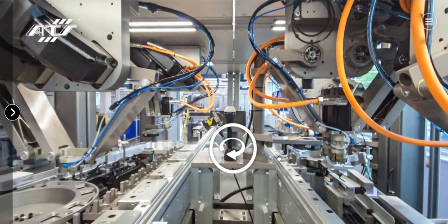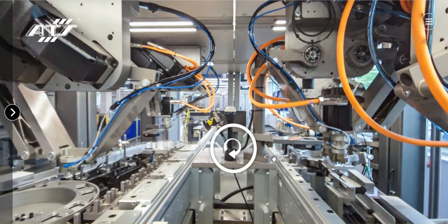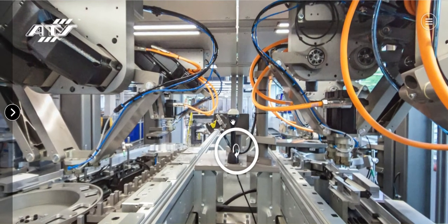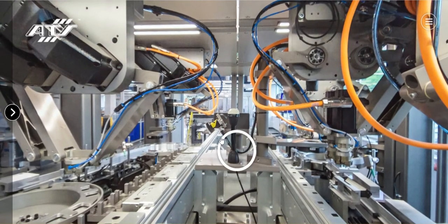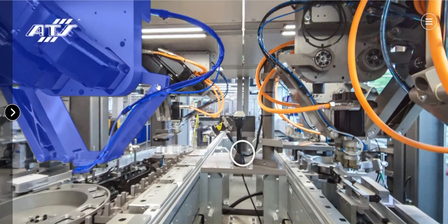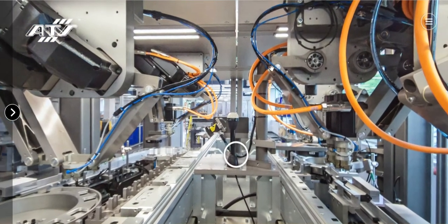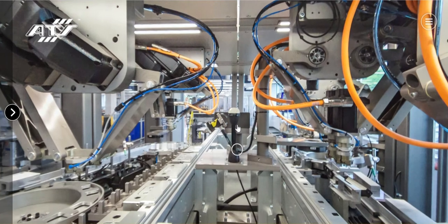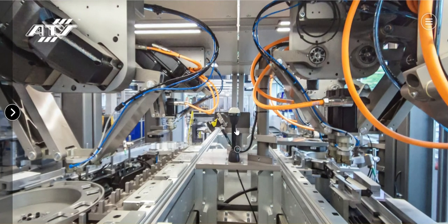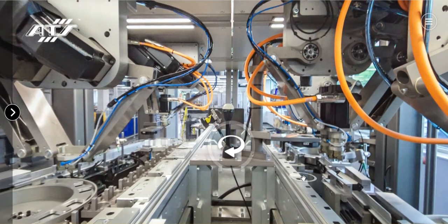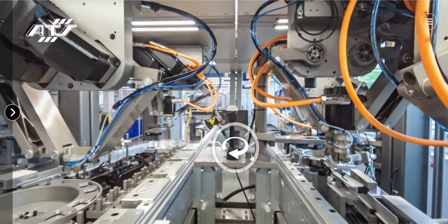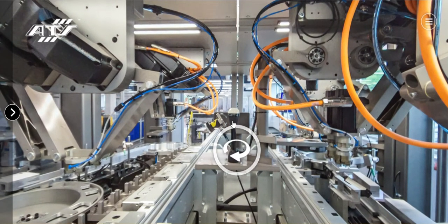When we want to restart the machine, because of the possibility of this manual intervention, it could be the case that things are not put into good starting positions to allow the machine to start back up. That's what these indicator lights are for. You'll see indicator lights again here. This one corresponds to the pallet. Each individual robot has a similar indicator light on it. This light will change colors depending on whether or not pallets are in a position safe to restart the machine. If they are not in a safe position, the light will be red.